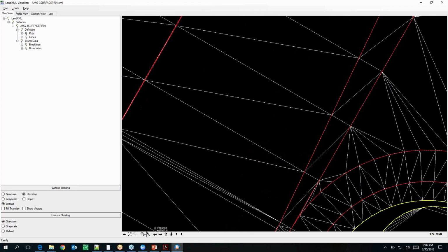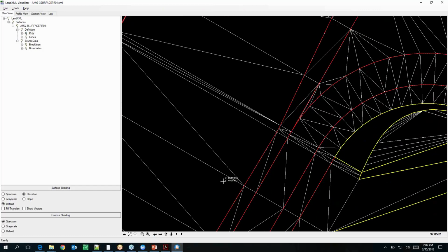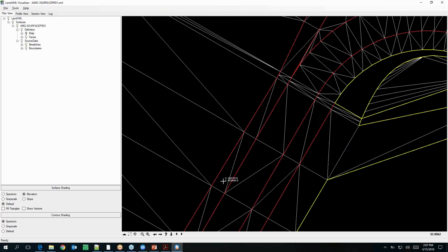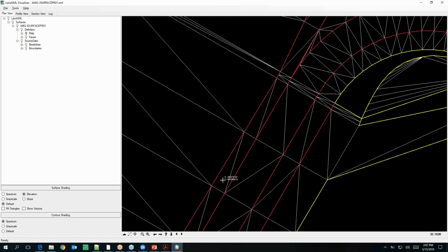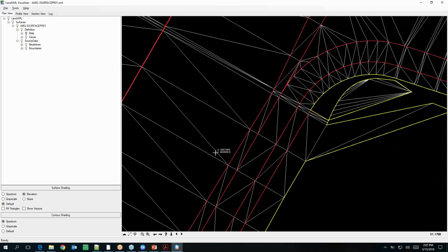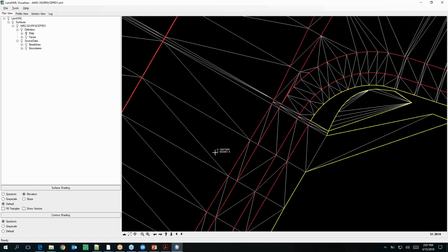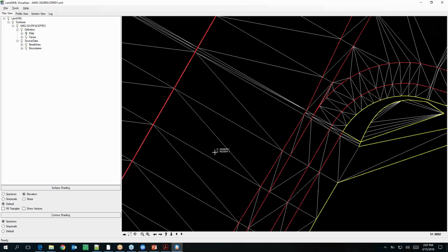So it probably has an issue with our corridor model. Actually, no. What that is, if you look at the middle crown, there are some extra points in the middle of the pavement, probably, that it tries to triangulate that edge too. So it just happens to have more points.